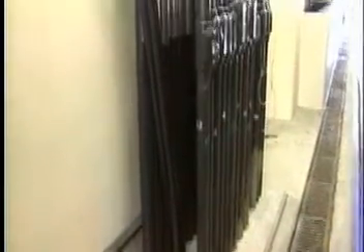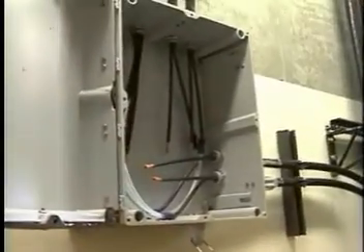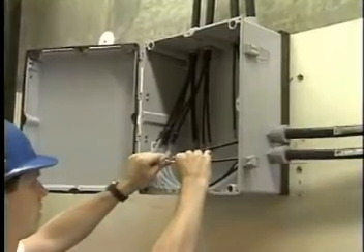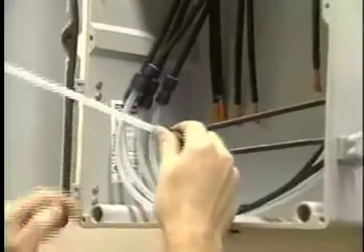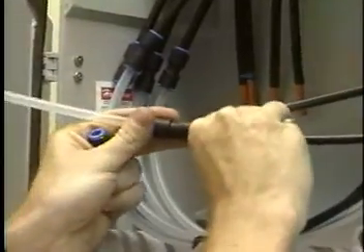The number of tubes in the cable will depend on the present and future application of the system. Junction boxes are used to interconnect the tubes of various cables using small push-fit connectors. This method eliminates much of the splicing and connectorization involved in complex fiber runs.